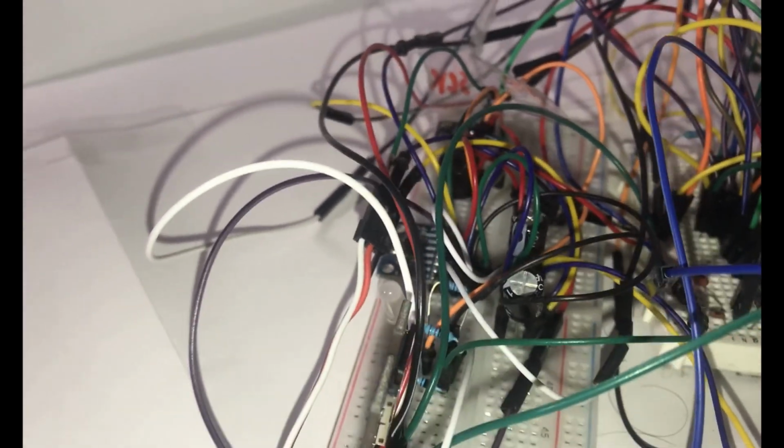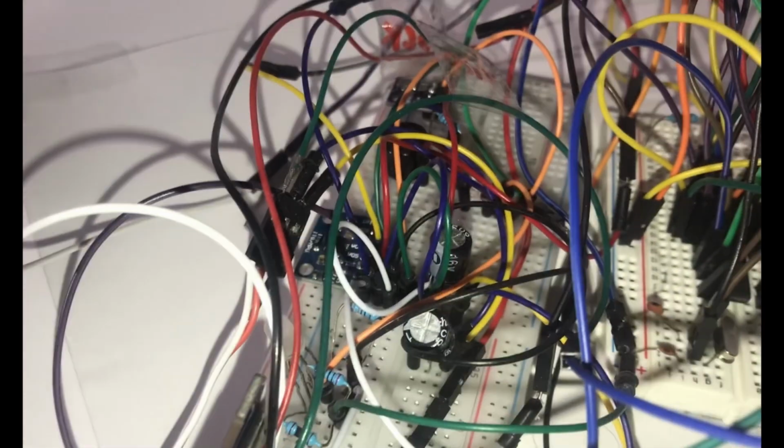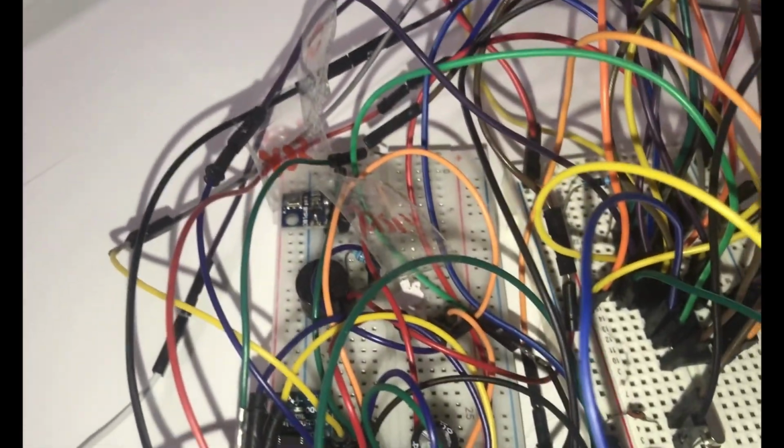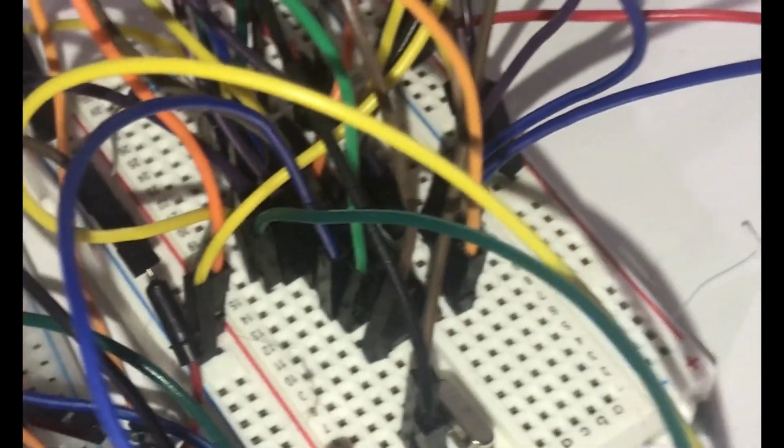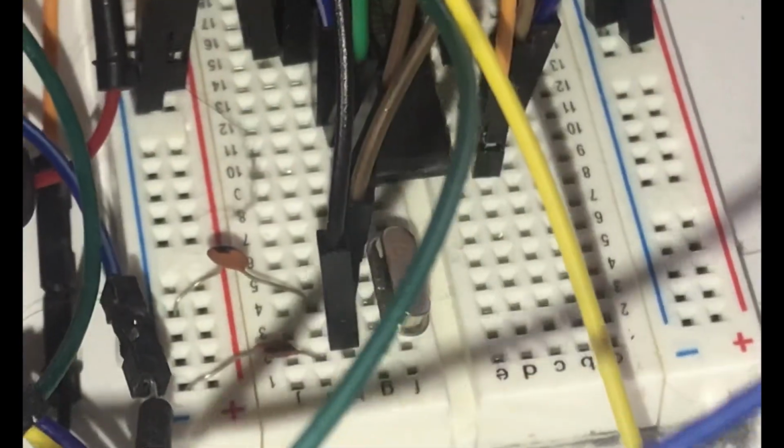The TRAPPIST-1 flight computer has been designed to have a micro SD card support, such as a data logger, a 6-axis gyroscope accelerometer MPU 6050, an RGB LED, a buzzer, a BMP 180 barometer, and the brain of the whole flight computer, that is an ATmega 328P. An Atmel AVR chip with 32 pins, 32 KB of flash, 2048 bytes of RAM, 1024 bytes of EEPROM, and 20 MHz of frequency.